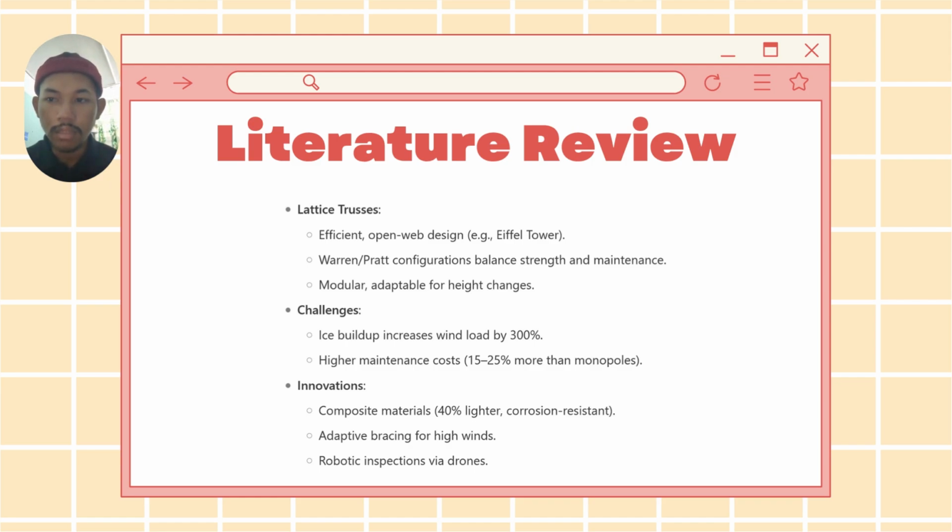Ice build-up can increase wind load by 300%, and their open design requires 15 to 25% more maintenance than monopoles. Thankfully, innovations like lightweight composite materials, adaptive bracing for high winds, and drone-assisted inspection are addressing these issues.